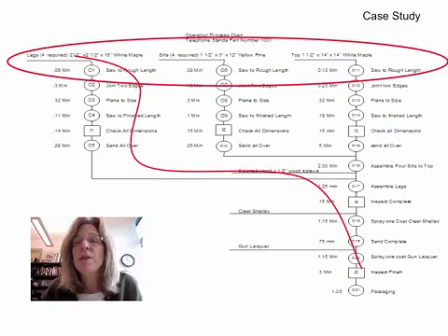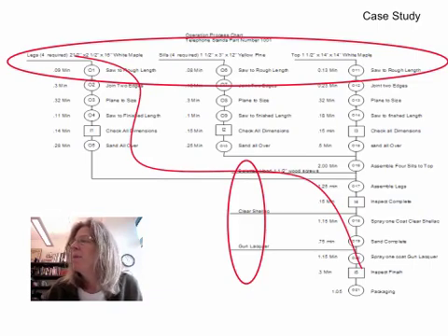Also, everything that's a horizontal line is indicated something that is made or processed for this particular part. Everything that's a vertical line is something that's processed. Everything that's a horizontal line is something that's purchased. Got those mixed up, sorry. But the purchased parts here would be the clear shellac and the wood screws and the glue. And the made parts are going to be the legs, the sills, and the tops. So you can see that the ones that are purchased have no processes associated with them. They could have an inspection, but in this case they don't.